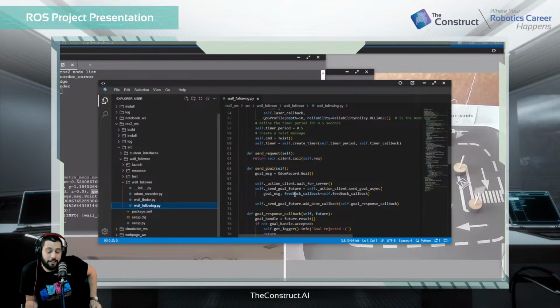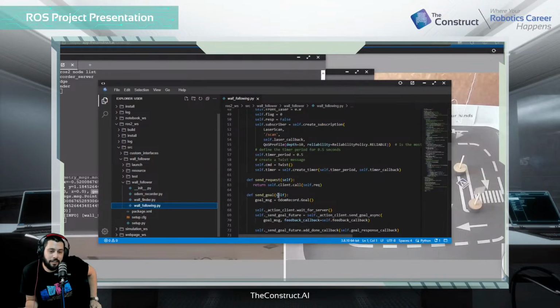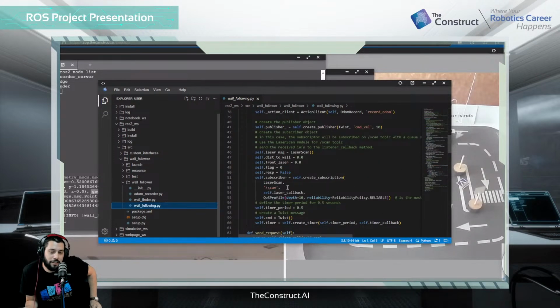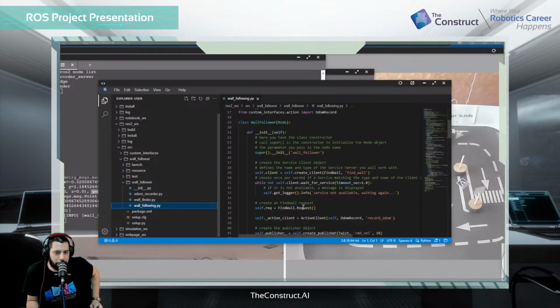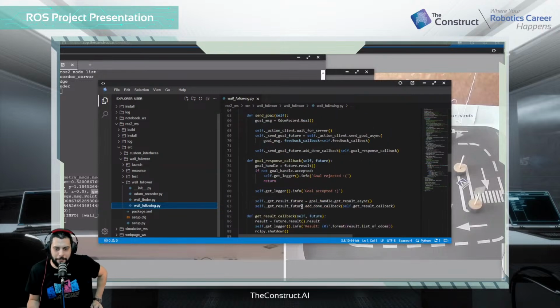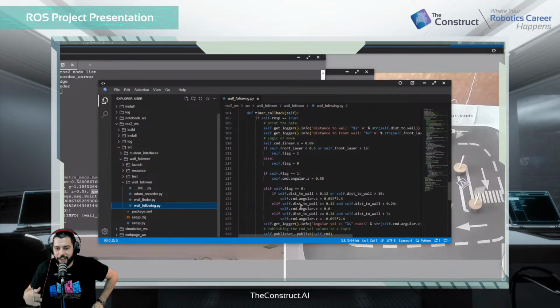That's interesting. Yes, for me that was the way it worked, because when I tried to do it in the main callback, I had problems with the readings of the sensor. It was not reading the sensors properly. I'm not sure really why, but when I used the timer callback, the laser sensors are actually updating correctly, and then it worked for me. So that's why I used the timer callback instead of the callback function directly from the action server. Hey, that's good. I thought it was interesting. It was really nice, elegant for the callback. You just set a flag and let the timer do its thing. That's great. Yes.